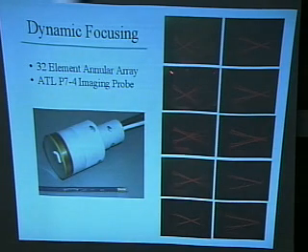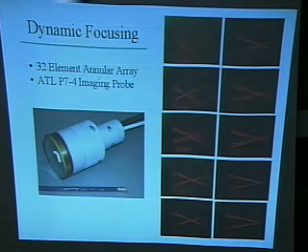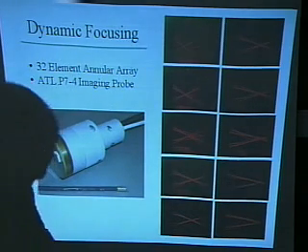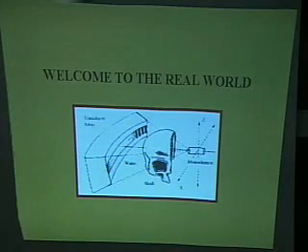And what we are seeing here is Schlieren imaging, a way of visualizing an ultrasound beam. We are seeing focal spots from 4 centimeters away from this transducer all the way to 13 centimeters. So you could actually step your focus. I think I went fast enough to now get to the fun part, maybe a little bit.